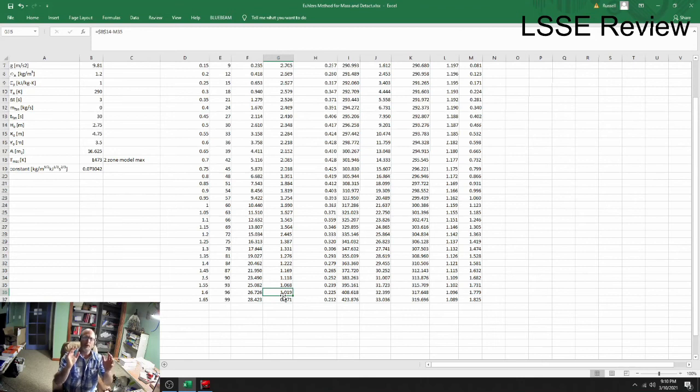So if you're in a room, tenability, according to NFPA 92, is defined as having a smoke layer that's above 6 feet. Now, technically, Annex A of NFPA 101, Section 5.2.2, gives you 4 criteria for tenability that you could apply.